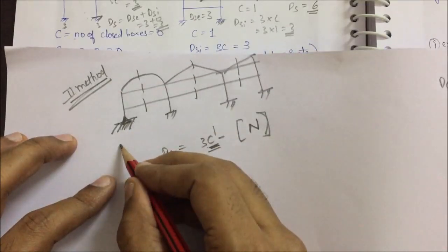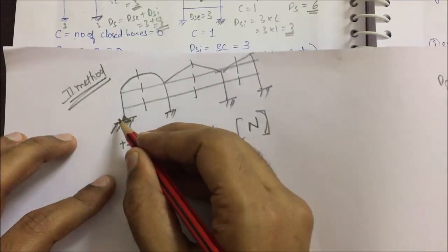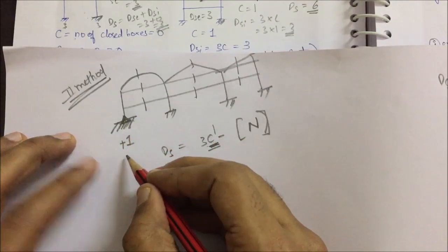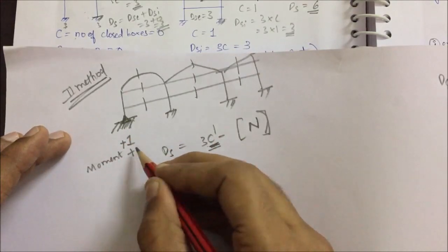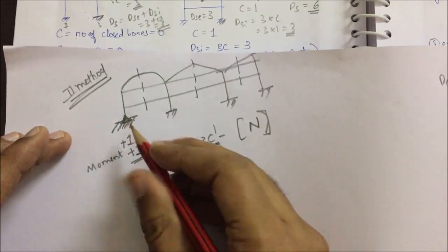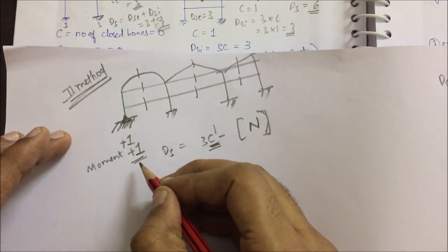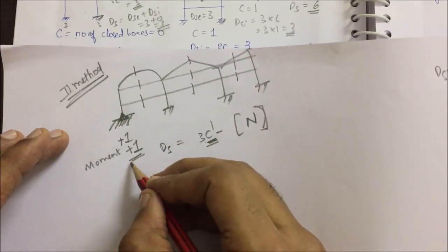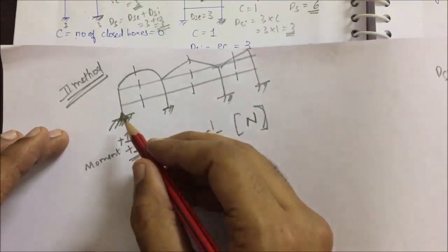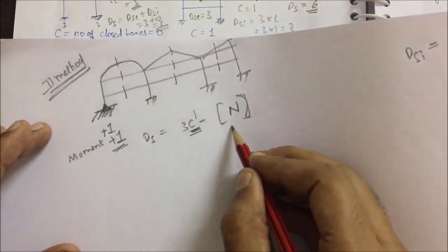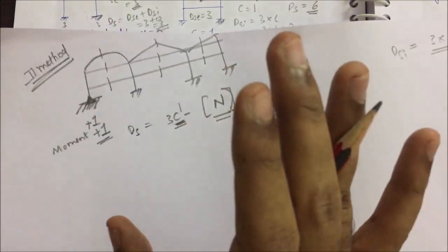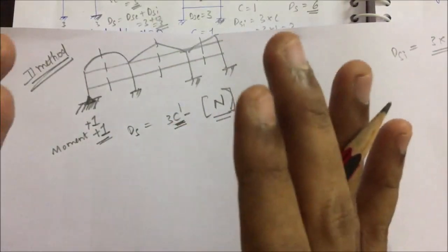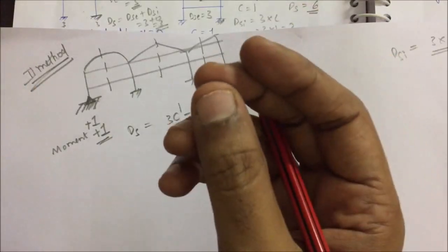So you are adding one more reaction. Earlier there was no moment, now we are adding that moment, right? So the moment is the extra reaction which you have added to make your pin joint a fixed joint. The reaction that you are unnecessarily adding to make it a stable cantilever, you have to subtract here. You will be getting a direct answer. It is quite simple, don't worry. Don't think this method is long. If you do 2 examples now, you will solve this question within 30 seconds.